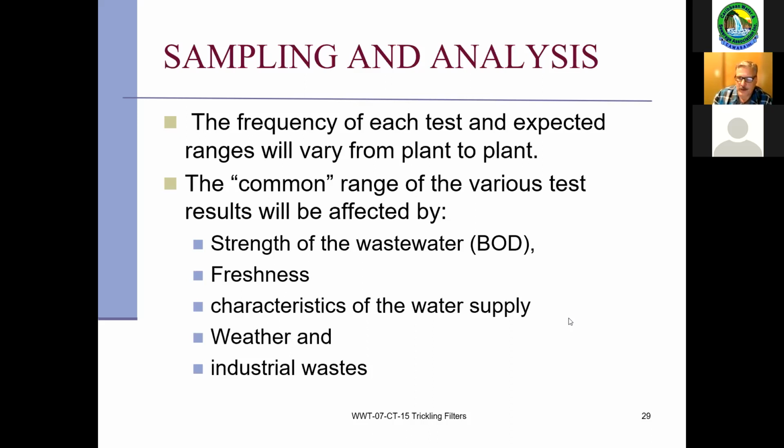The flow is going to be slowed down in the winter because your biological activity in that filter media, although you've got a good media and a good biomass, as the temperature drops, just like any biological plant, you need more time to do the same work.